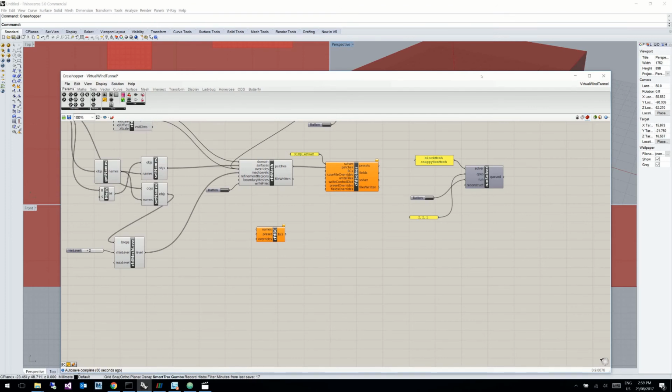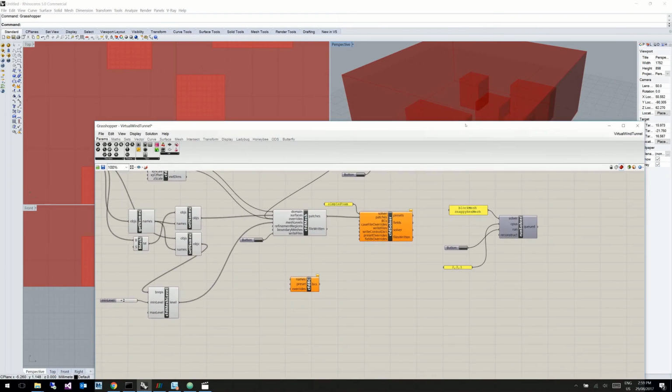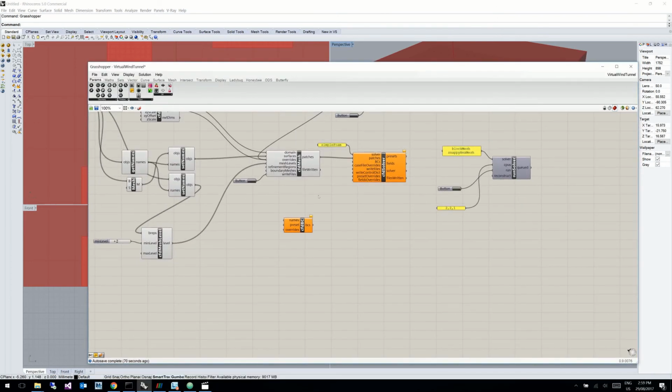We'll keep all the default wall conditions as they are. However, we want to define an inlet flow velocity of 5 meters per second on the max-y. So we'll override those, and we'll set an outlet boundary condition of fixed pressure on the min-y side. So to do that, we add a panel and set max-y.